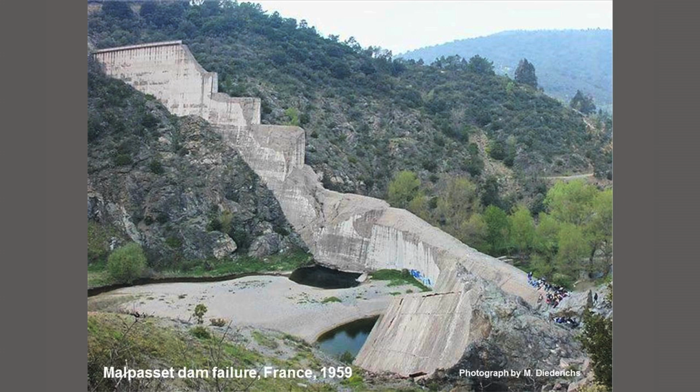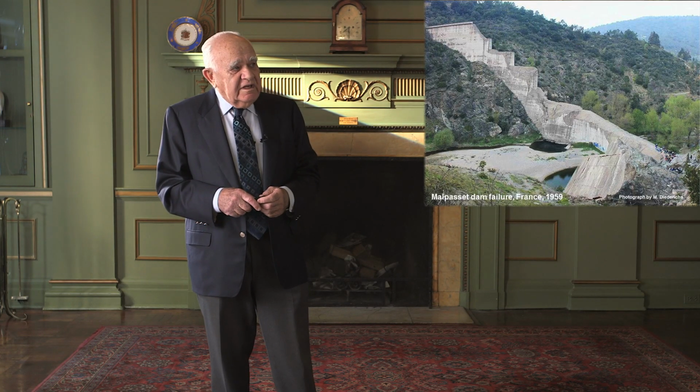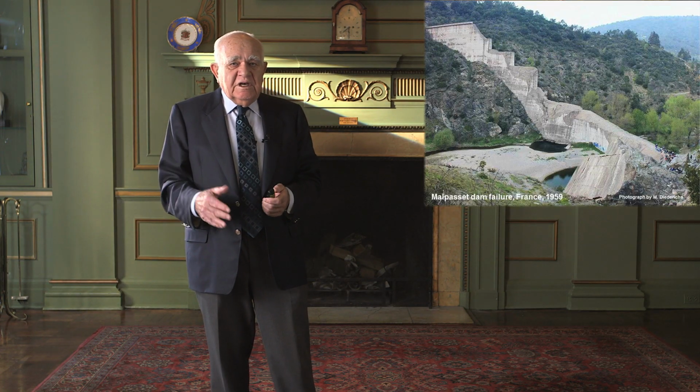And this slide illustrates a dam in France, the Malpasset Dam, which failed in December 1959 during filling of the dam. And it's a concrete arch dam, so you're looking upstream at the reservoir, you're standing downstream of the dam. And the failure was caused by a fault within the reservoir, which seemed to be safe when you looked at the mechanics, but the loading of the water pressure created as the reservoir was filled caused that fault to slip and the dam to fail.